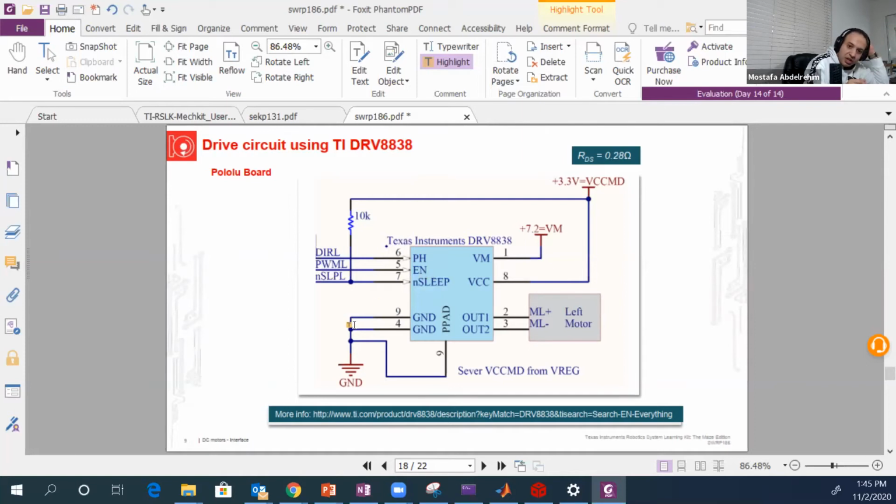Pin 5 is called enable. Okay, just forget about its name. It's actually used to control the speed. We will see that in 2 or 3 lectures. But for now, if you put 1 there, the motor will run with its full speed. If you put 0, the motor will not run. So this is how you can understand how it basically controls the speed.